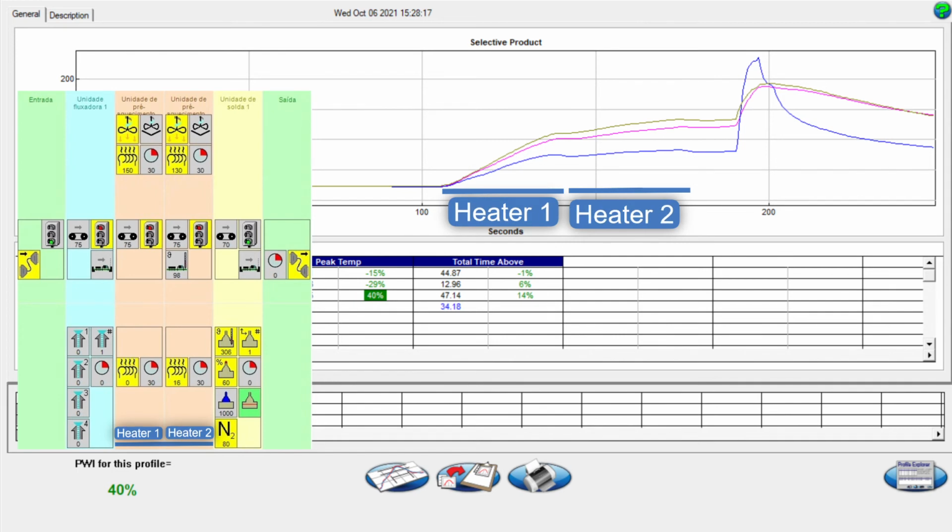In the selective solder machine example, it's possible to modify the temperature set point, the time the board pallets stop in the two preheating zones, and other set points. The modification of the set points will create an impact in the time duration that the board is heated up on each preheat zone, as well as the ratio of heat transferred to the board. Increase or decrease set points accordingly with your optimization goals.